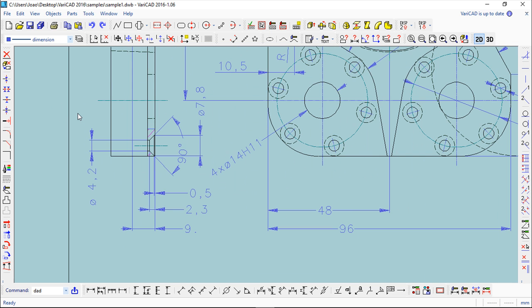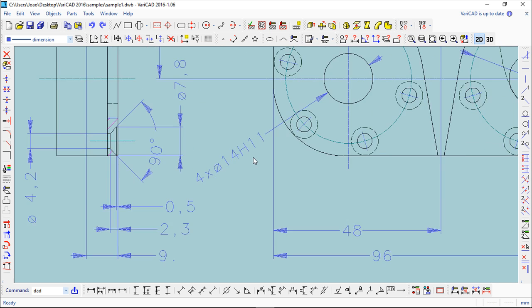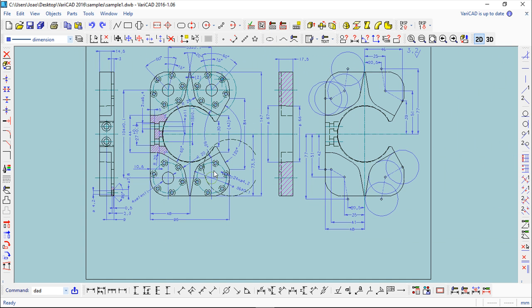Okay, and I can restore immediately these portions of the drawing that I've saved, restore view 1, or restore view 2, and it doesn't matter what I have drawn or what I have created in my drawing. These functions just care with a portion of the screen that I've saved. For an easier and faster access, I can go here to the restore. I can have up to 8 views, or the save here. It's exactly the same. Now restore 1, restore 2, which is the same. So basically these are the functions related with the views.